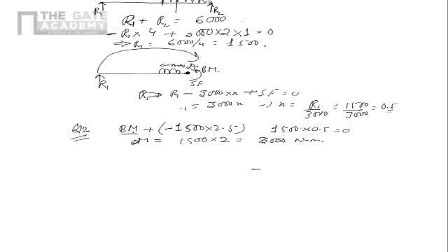So that makes it minus 1500, which is the value of R1, into the distance, which is 2.5, plus the counterclockwise moment because of the distributed force. The distributed force is 3000 Newton per meter multiplied by the span, which is 0.5. So that makes it 1500 multiplied by the gap between the center of that force and the point D, which is nothing but 0.5 by 2. Sorry, this is 0.5 by 2. Right, so this is not 3500 now. It is something else.